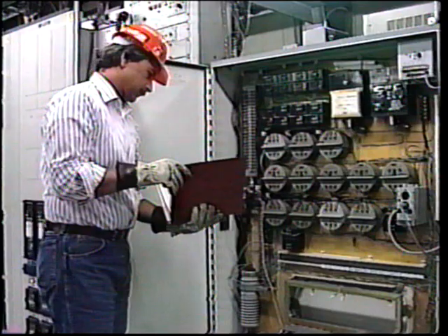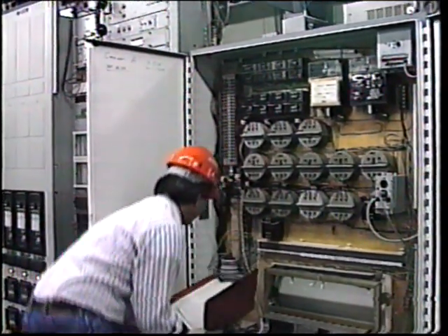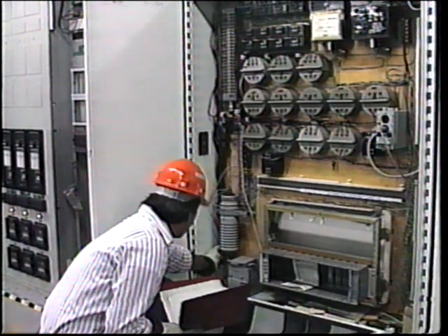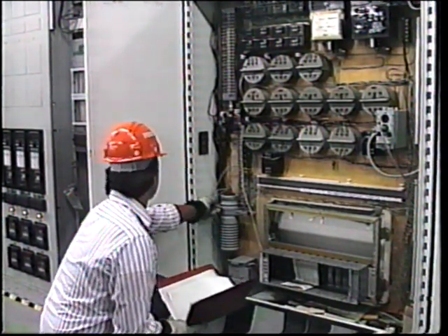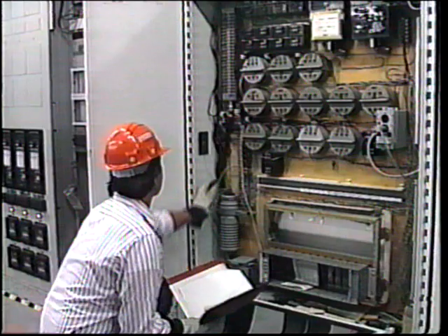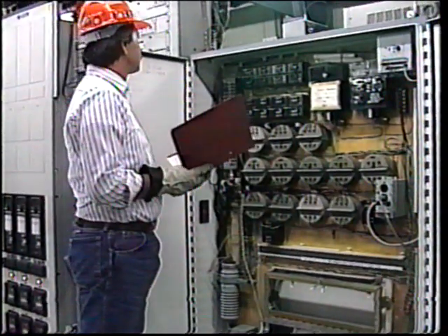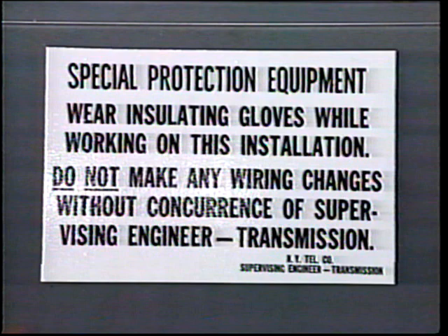Whenever work is performed around HVSP equipment, safety precautions should be observed. Most utilities stipulate that appropriately rated rubber gloves must be worn when working on the circuit. As we mentioned before, some, but not all, power and telephone companies recommend thick rubber mats be used. Large warning signs are posted to indicate the potential danger.